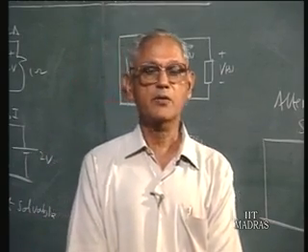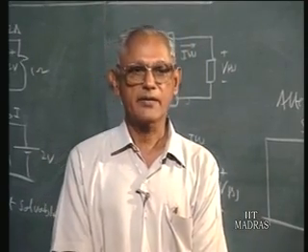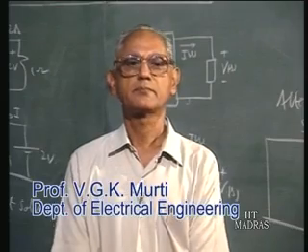replaced by a short circuit, the current source is replaced by an open circuit. And this is to be done for all independent sources. Dependent sources, if there are any, must be kept intact. They are part of the linear system.